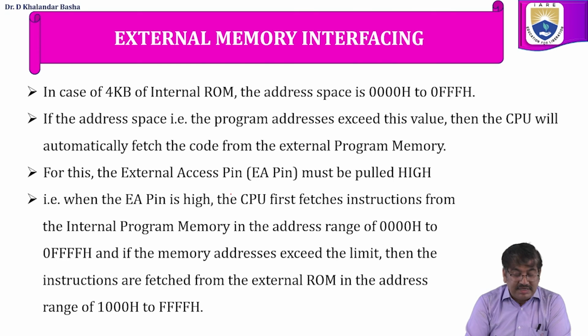That is, when the external access pin is high, the CPU first fetches from the internal program memory, that is from the address 0000H to 0FFFH. If the program address exceeds the limit, then the instructions are fetched from the external ROM, that is from 1000H to FFFFH.